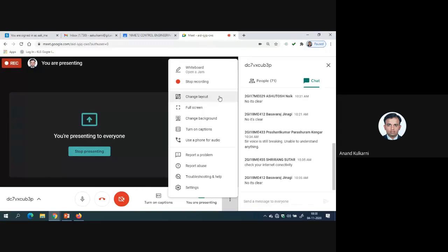Applications of armature controlled DC motor or field controlled DC motor are where you want a variable speed drive at a very cheap rate. For example, in our lab, almost all labs, there is a design lab. Wherever we are using a variable speed drive, for most cases, like say the governor experiment, it is armature controlled DC motor only, basically because it is very cheap and we are not much bothered about the losses. But when you come across losses, DC drives are not preferred over AC drives. The reason is the losses in DC drives are always higher.